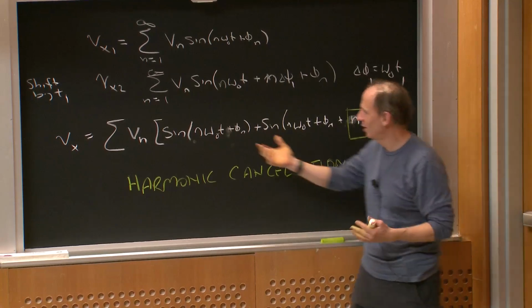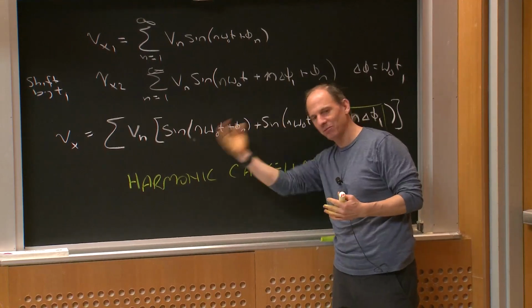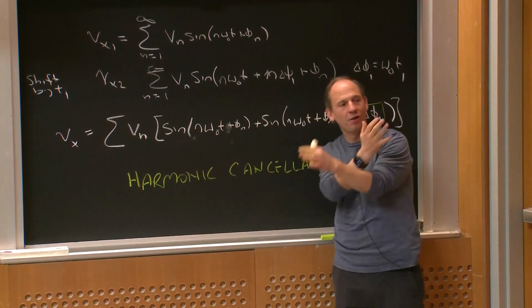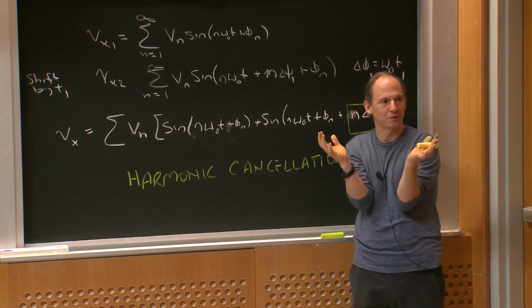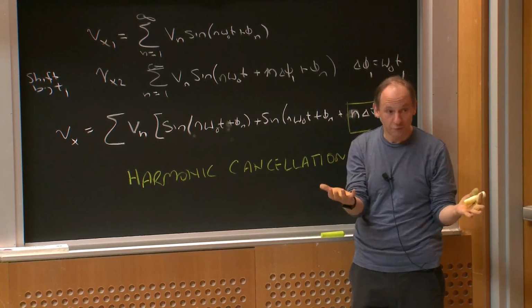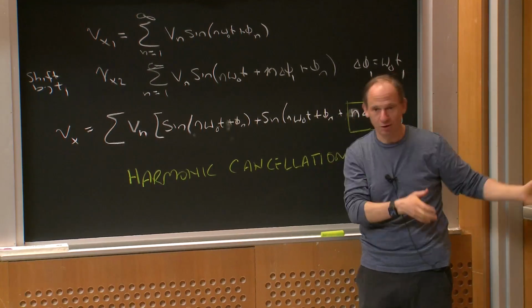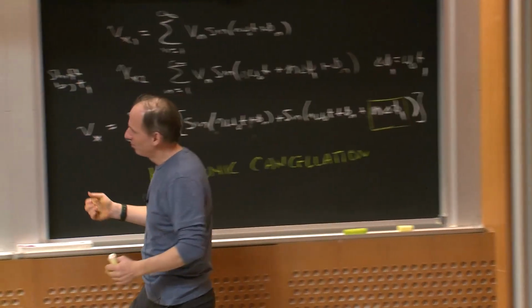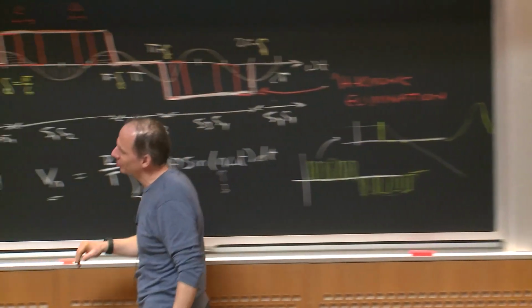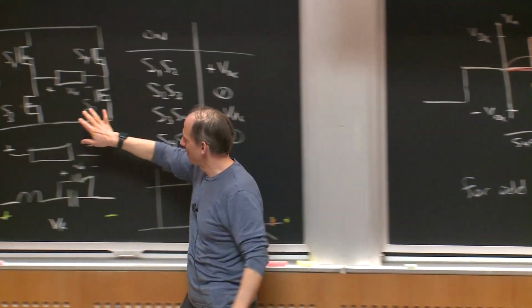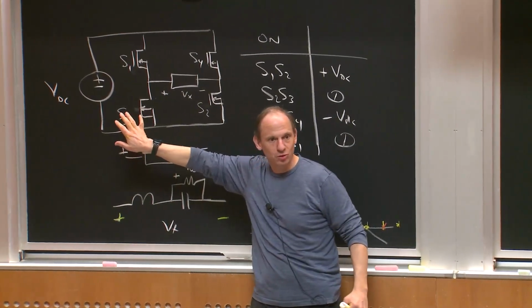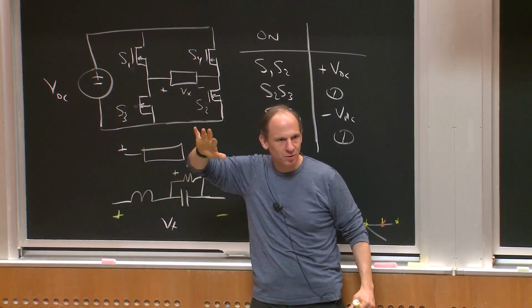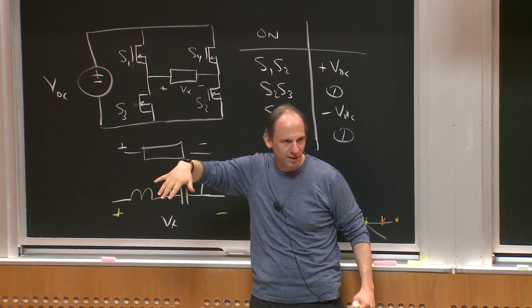In other words, if I take two half-size waveforms and add them up, the most I'm going to get is back to the original. Other than that, I'm just going to get some degree of cancellation. So I don't introduce new frequencies by doing this trick. I just kill frequencies. So my original waveform, because it's a harmonic cancellation of the two half bridges, I have no triplen harmonics, no 3, 6, 9, 12, 15, 18, and so forth, right?